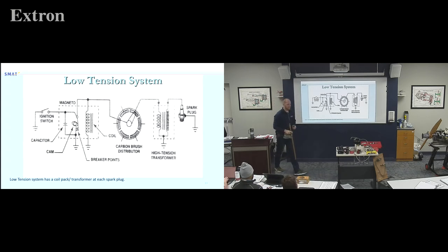Yes, Leo. So we're still talking stepping up voltage, though, right? Correct. So why does that make a difference on wiring if voltage is not really the issue? Your wire insulation is going to be rated at a certain voltage, right? Not current, or amps. The insulation specifically is voltage. The wire size is amperage.